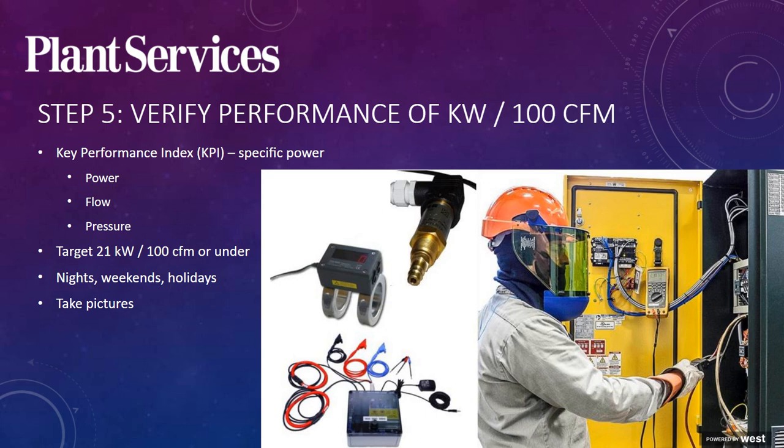Again, take pictures so you can show that before and after to your management team. There should be nice, new, shiny equipment, and everybody should take ownership over that. Lastly, target that KPI under 21 kilowatt per 100 CFM.